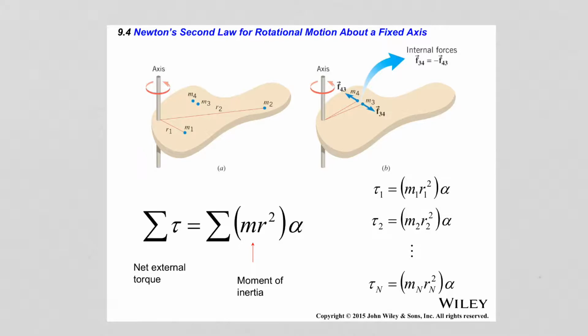of this rigid body. Notice that the moment of inertia of this rigid body depends on the product of the mass and the distance to the axis of rotation to the second power, and it is a sum of individual terms that correspond to these particles. So each term has a different value because each particle has a different mass and each particle is a different distance from the axis of rotation. So that means that the moment of inertia here is a function of the mass distribution inside this rigid body.